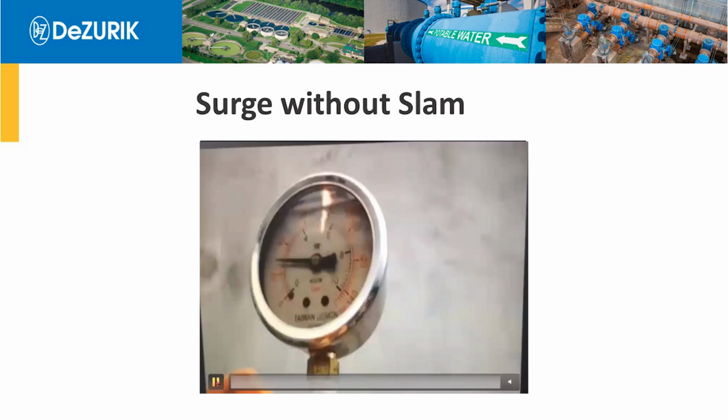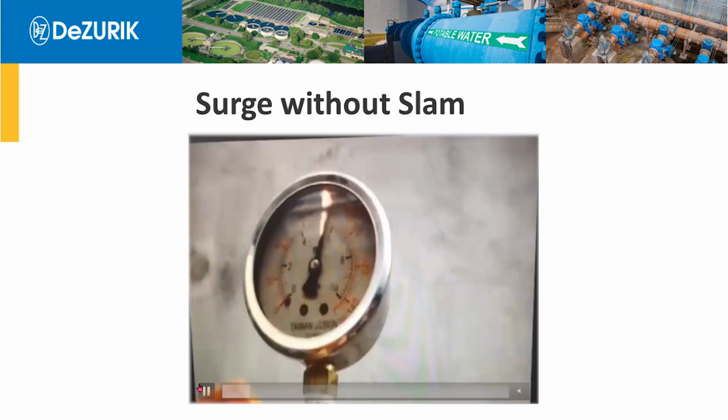With a check valve, whether it's a slanting disc or a silent check or a lever and weight, lever and spring, air cushion, or a ball valve or cone valve, we can get those valves to close quickly on loss of power to protect the pump from backspin. And they can close quickly, and they can also close quietly without slam. But just because they close quietly does not mean that you're not going to have problems in your pump station.